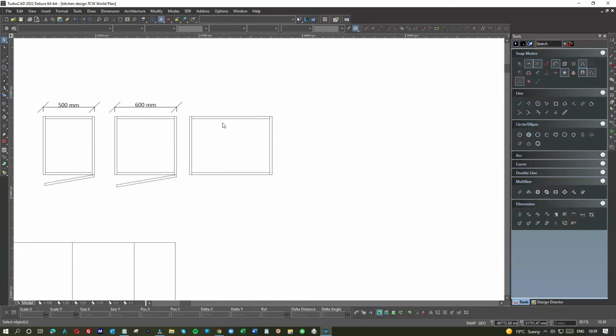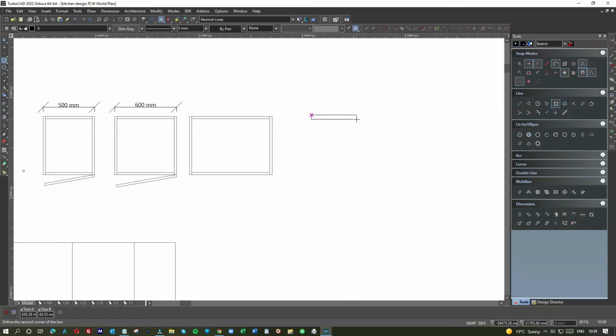So let's make a door for the unit. Again, it's an 800 unit, so we wouldn't have an 800 door because it'd be too heavy. It'd be falling down on one side. After you hang it, after a little while, it's going to fall down. So what we'd end up with is two 400s. So let's do a 400 door for starters. And again, the door is 22 mil. So tab 400, tab 22. And that's a standard door.